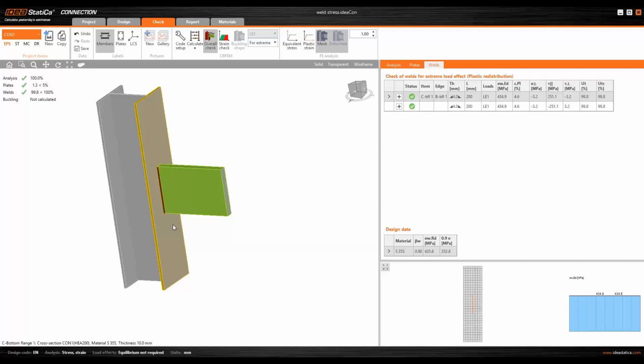I think, Adam, it's usually that you have to disconnect all entities, right? Yes. Usually you have some objects in AutoCAD, so please try to disconnect them to really simple. Yes, explode. If you want to import a DXF, it has to be in the most simple form.